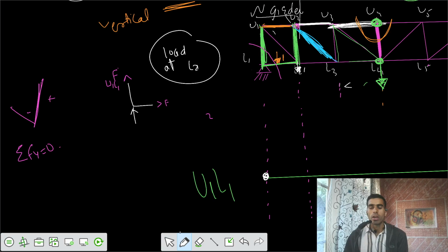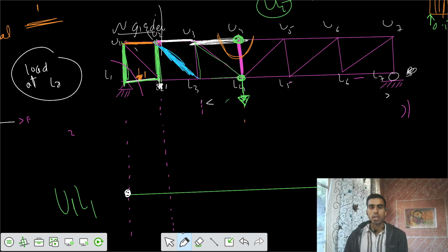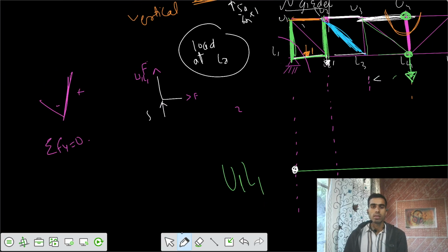That's 5/6, because in the total span we have 6 segments. Think of a beam subjected to a load at a location of A and 5A. The reaction here is 5A by 6A into that unit of 1. So 5/6. The reaction is 5/6.